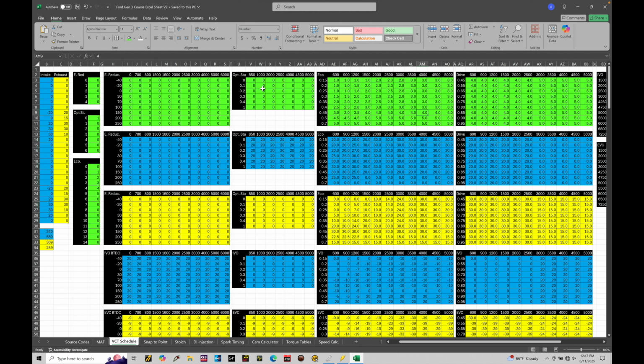Even in optimal stability here, if we call out 0, that's going to be translating here into the MAP point 1. And if we call out a value of 1, that'll be our MAP point 0. And in here, in our eco and drivability, if I call out a 0 in either of these two tables, that'll actually call out MAP point 0. So we want to change our optimal stability to 1, and we want to change our eco and drivability tables to 0. So we're staying locked onto MAP point 0. Hope that makes sense.